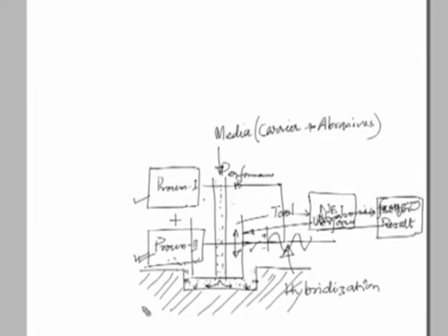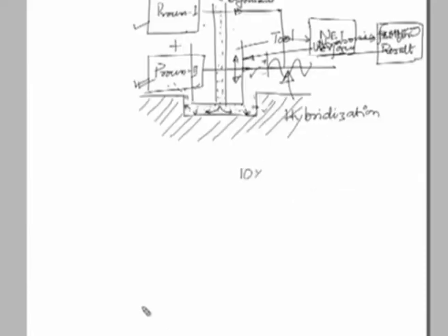And now, as a result of this enhanced velocity, this will abrade this workpiece material at a faster rate, and therefore, the material removal on this workpiece surface is expected to be much higher, and also 10 times better surface finish have been reported. The vibrating tool ultrasonically energizes this mix, as I have already told,